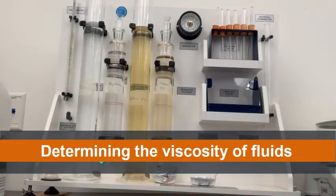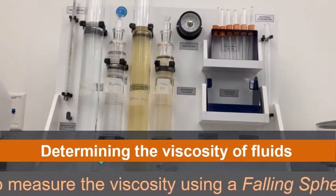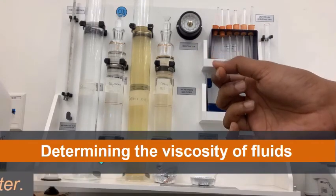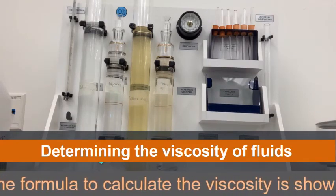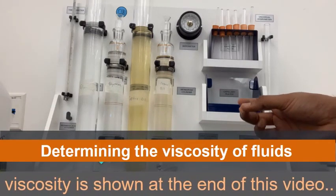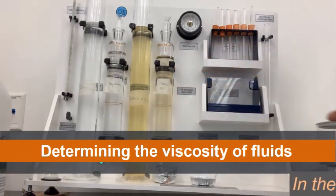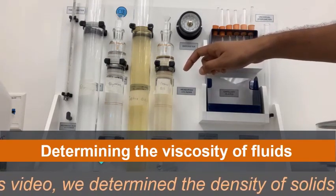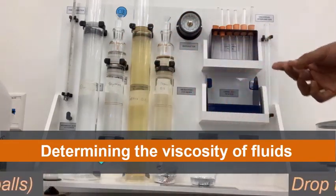So in this procedure, using the falling sphere viscometer, we are going to determine the viscosity of the substance using these metal balls, for which we are going to record the time of fall and the length of fall. So here for the castor oil, we will drop the metal ball, and also for the glycerin. Just the same procedure for each of the fluids.